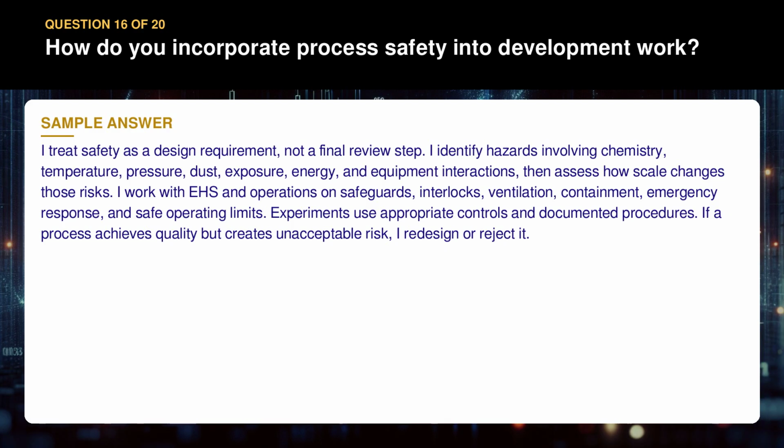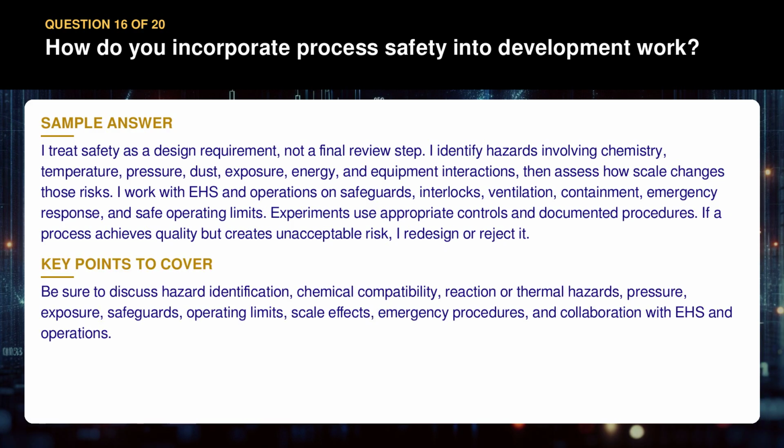Experiments use appropriate controls and documented procedures. If a process achieves quality but creates unacceptable risk, I redesign or reject it. Be sure to discuss hazard identification, chemical compatibility, reaction or thermal hazards, pressure, exposure, safeguards, operating limits, scale effects, emergency procedures, and collaboration with EHS and operations.